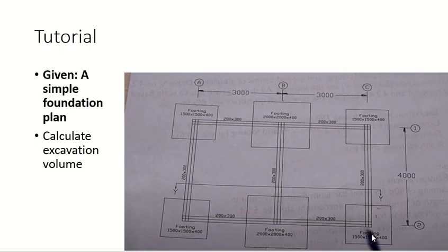I was telling you that we did the excavation work earlier, right? We calculated the amount of excavation required. We wanted the ground level as 1.5 meters deep. We calculated the average and so on and so forth, right? This is another scenario, where the excavation is done for each footing separately. This is more common for villas and buildings. Each footing is excavated separately. So you will not do one level for the entire site. You will say, I have footings and I want the footing excavation done.